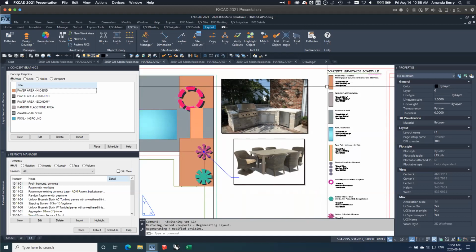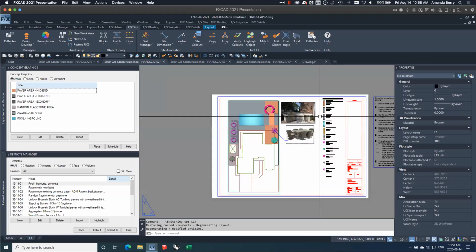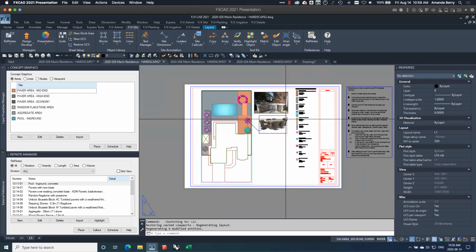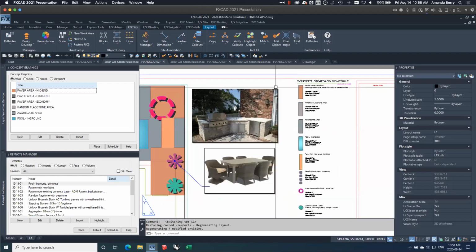So go for a smaller image size in general, because when you export from CAD, it only exports as vector. There's no way to export as render to a PDF straight from CAD, or is it vector and raster? You can only do vector. So when you do vector PDF, it's actually including the image scaled down. So if it was a 5,000 pixel 15 megabyte image to begin with, then it's still that 15 megabyte image just scaled down, and now in a larger PDF you start to see that's how you add up all of that